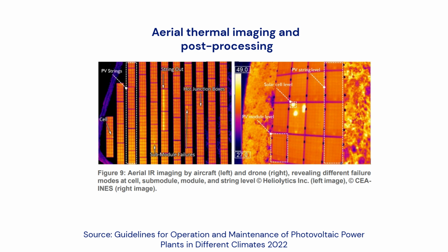Thermal imagery-based inspections refer to the process of collecting and analyzing infrared images of photovoltaic systems. Today, this has become a widely accepted best practice, and infrared inspections of PV plants are most commonly carried out using aerial methods. By analyzing abnormal temperature variations and thermal patterns across the inspected PV arrays, it is possible to locate and diagnose almost any critical defect or failure, even those that cause only minor performance losses. At the same time, this approach allows for the early detection of hot spots and potential fire risks. These infrared scans can be used either alongside manual electrical testing or, in some cases, as an alternative to it.